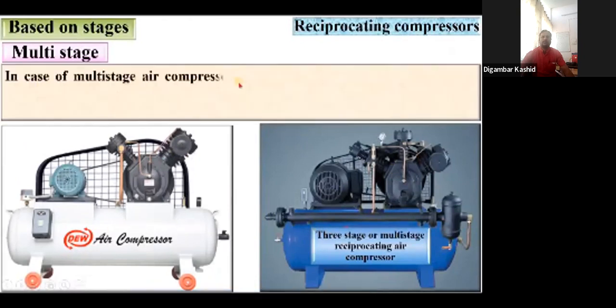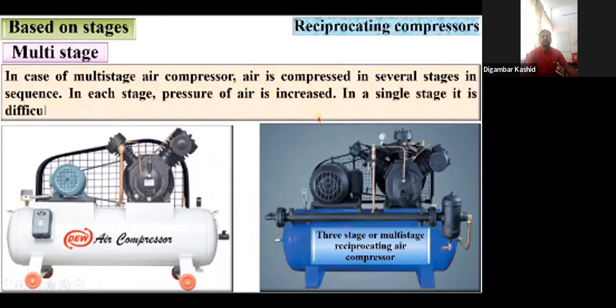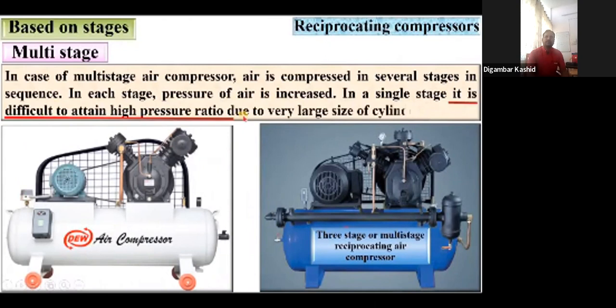In case of multi-stage air compressor, air is compressed in several stages in sequence. In each stage, pressure of air is increased. In a single stage, it is difficult to attain high pressure ratio due to very large size of the cylinder. So at that time, multi-stage air compressor is preferred.